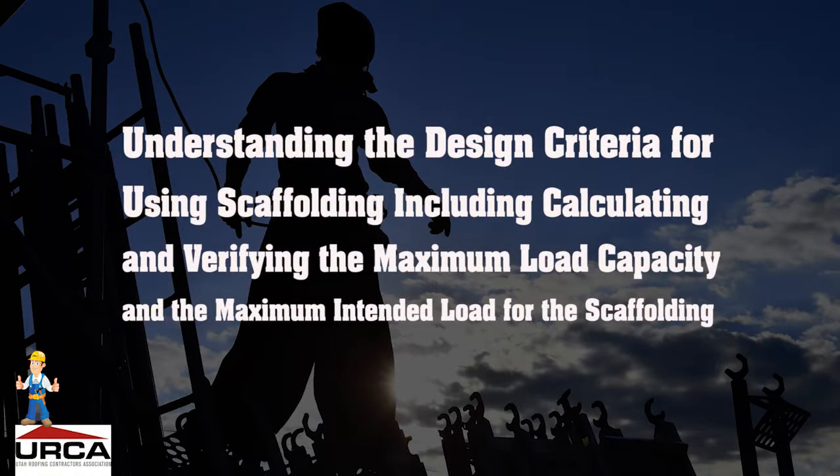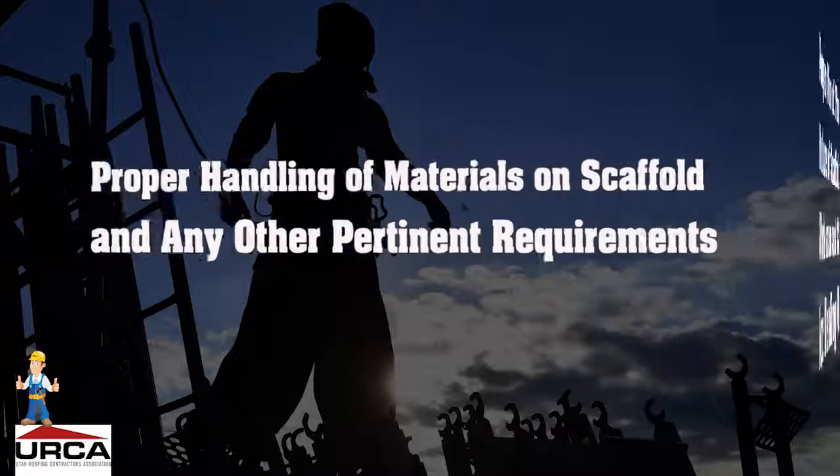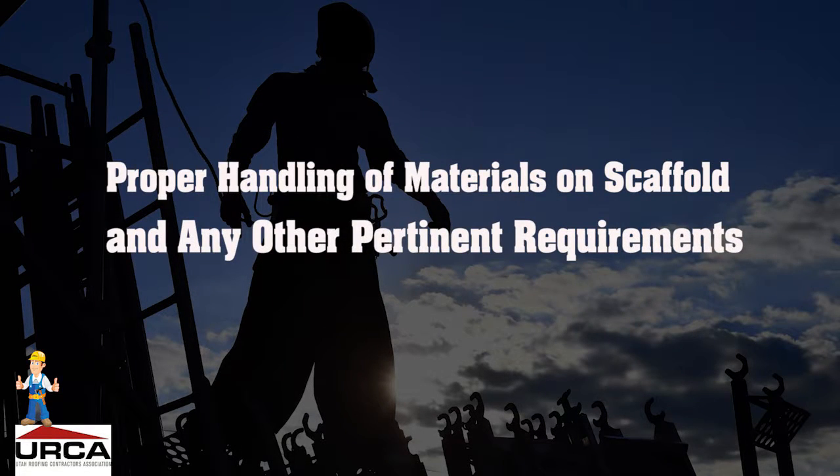Understanding the design criteria for using scaffolding, including calculating and verifying the maximum load capacity and the maximum intended load for the scaffolding. Proper use of the scaffold and the nature of the scaffold hazards in the work area and corrective action for dealing with hazards. Proper handling of materials on scaffold and any other pertinent requirements.